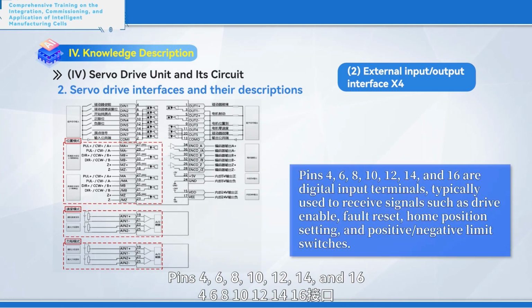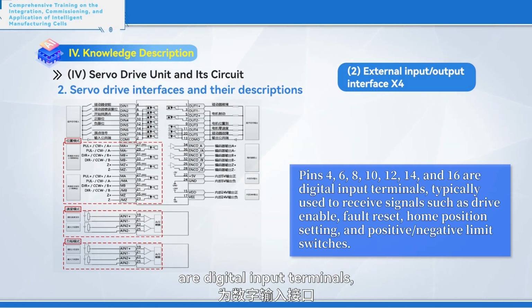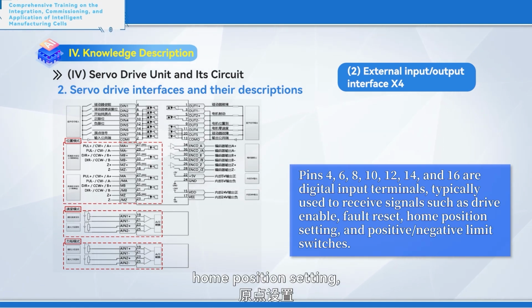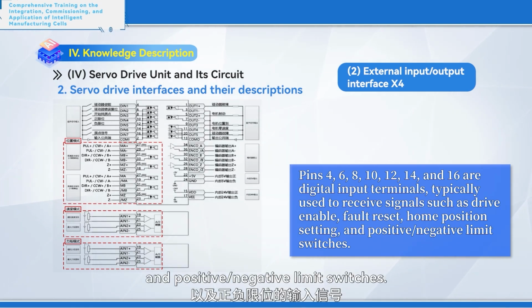Pins 4, 6, 8, 10, 12, 14, and 16 are digital input terminals, typically used to receive signals such as drive enable, fault reset, home position setting, and positive or negative limit switches.